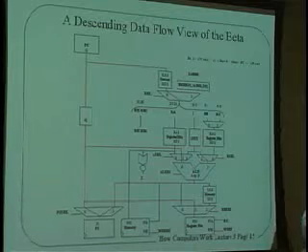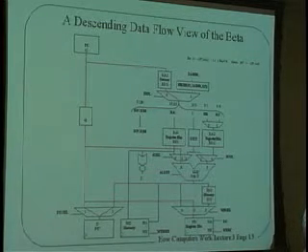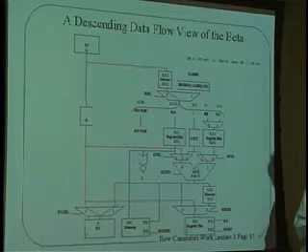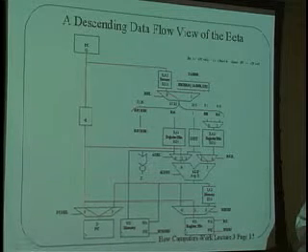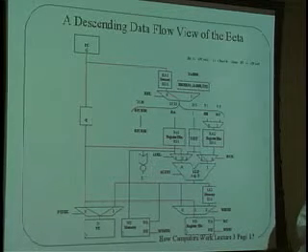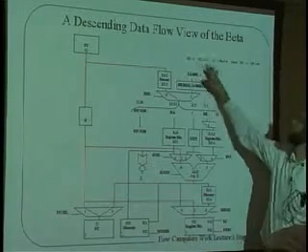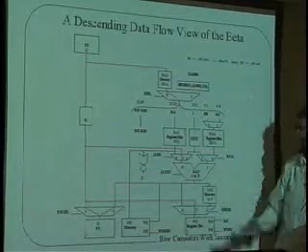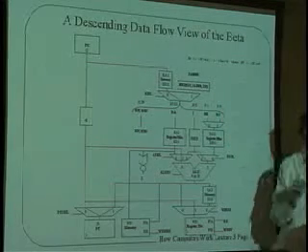And that's how we're going to do a conditional branch. So both those occur at the same time? Yeah, that's also a very good question, which is that I have effectively done this little sleight of hand. Before we said first the PC plus 1 gets put in here, and then we do this. And the answer is that this circuit that I've shown you with all these clocks going off at the same time does them both in parallel.